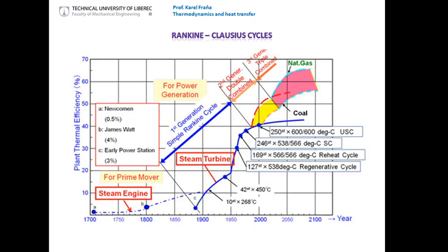And you can see the first thing you can do is just to increase the pressure difference between the saturated pressure, that means the pressure of the turbine, and the pressure of the condensation. First, they started at 127, they reached 30%, they increased to 169, and it increased the efficiency, and so on. So if you increase the pressure difference, you can increase the efficiency.